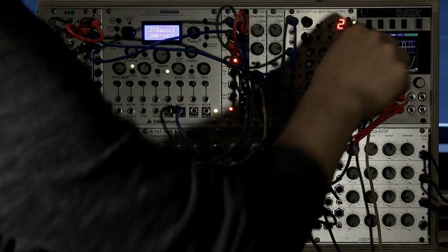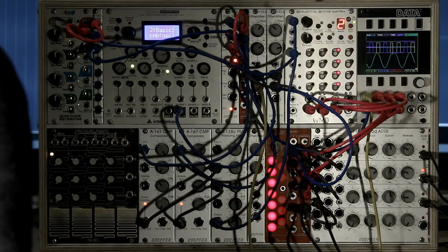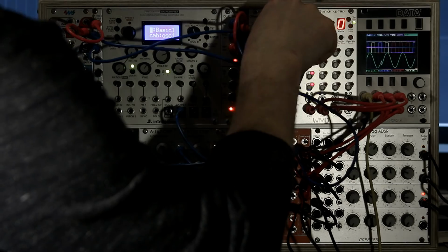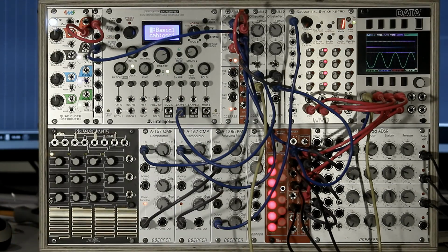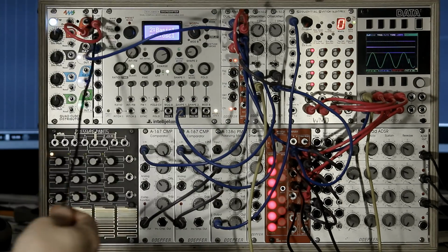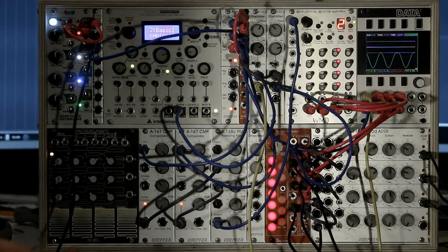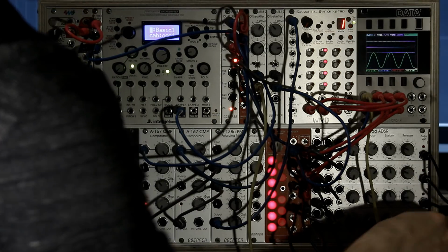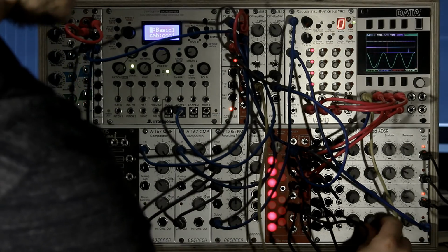Now you can hear that some more strange things are happening. The problem is synchronization of all those events. For example, the comparator change controlling the switch, the same clock signal sampling the LFO and triggering the Quantizer at the same time. To avoid any synchronization issues, we can slightly delay the clock signal triggering the Quantizer. So the Quantizer gates will be a little bit delayed.